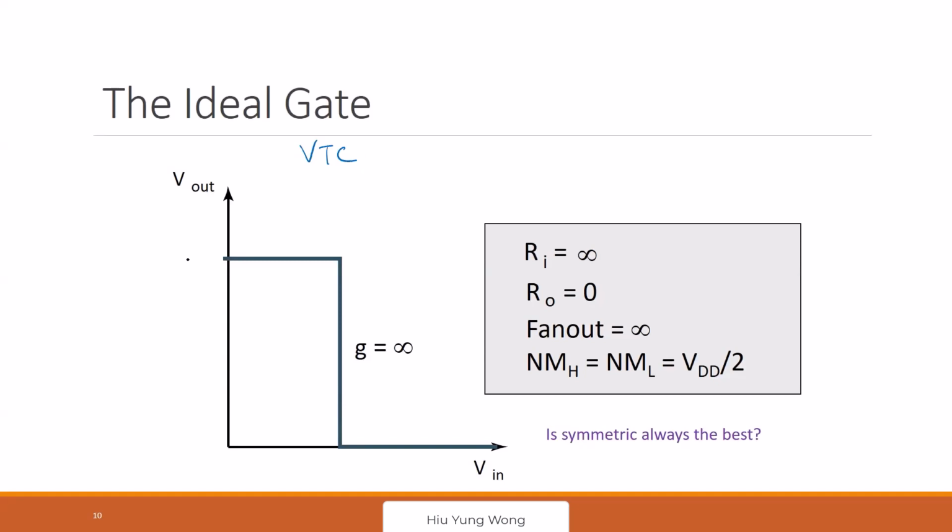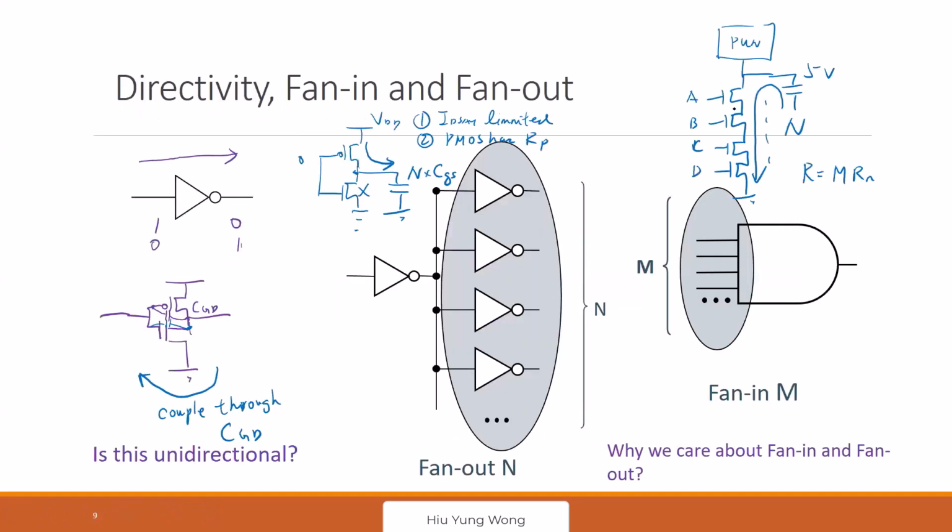If you can, try to annotate on my slide. But I think this one you know, VO high, right? And then this is VO low, correct? And then what is VM? This is VM at 45 degrees, right? And the ideal gate is what? I want to have infinite input impedance and 0 output impedance. Now, do you know? This is the output impedance I'm talking about.